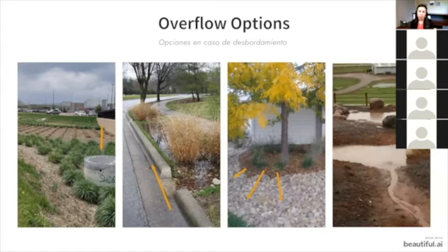In looking at the rain garden at my house, the overflow, once it's filled up, is actually over some rocks. It's stabilized right there, and it's not going towards a structure. There is a use, and I know where that overflow is going. The final picture shows how these rain gardens were dug and then connected together, so the overflow from one rain garden was directed into a different rain garden. There are multiple ways that you could do your overflow for a rain garden.